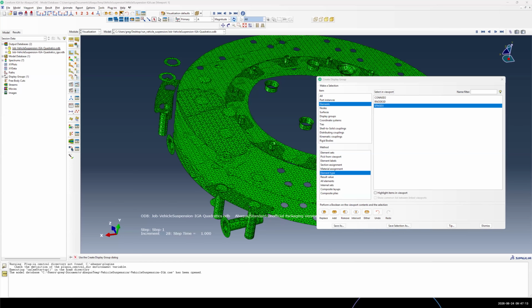Yeah, there's a difference between possible and implemented today. With IGA, you can definitely do birth and death routines. We've demonstrated it before for projectile penetrator simulations, showing element death. So you can definitely do it. We don't have that support today in the Coreform IGA for Abaqus. But again, we'd love to hear what your use case is and start talking about that. I actually personally think that when we start talking about things like additive manufacturing and wanting to be able to add material, IGA provides a really good framework for doing that in an efficient, robust, and accurate manner. But that's probably a topic for a later date.